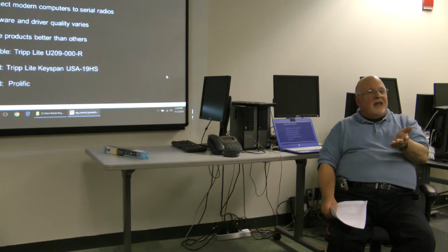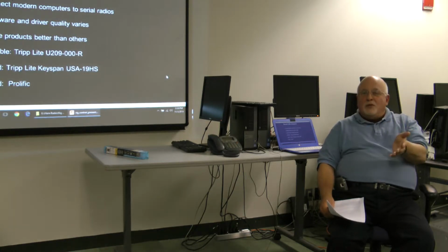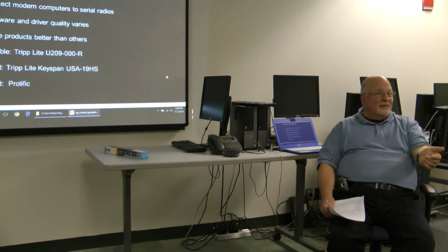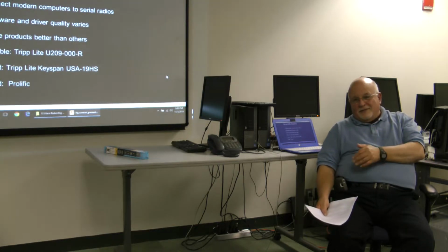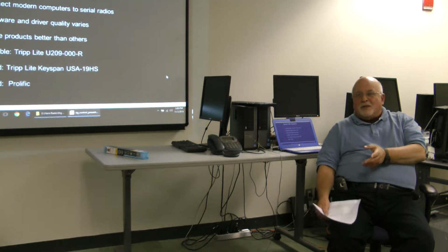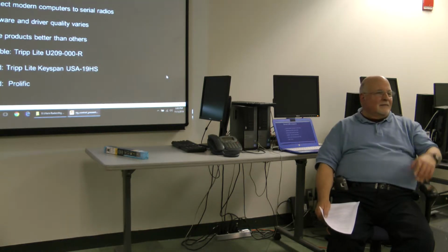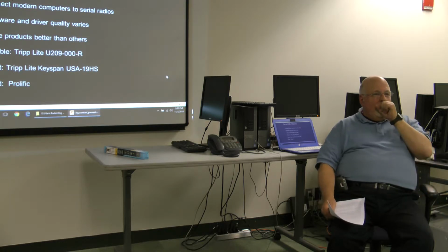And about every month they issue an update. So about every month, your cheap Prolific chip cable, not really a genuine Prolific chip, is going to stop working. And you got to go and reinstall the old driver. It's a pain in the rear, especially if you want to get something done, and I've got to go worry about updating this thing again before I can finally get on the air.